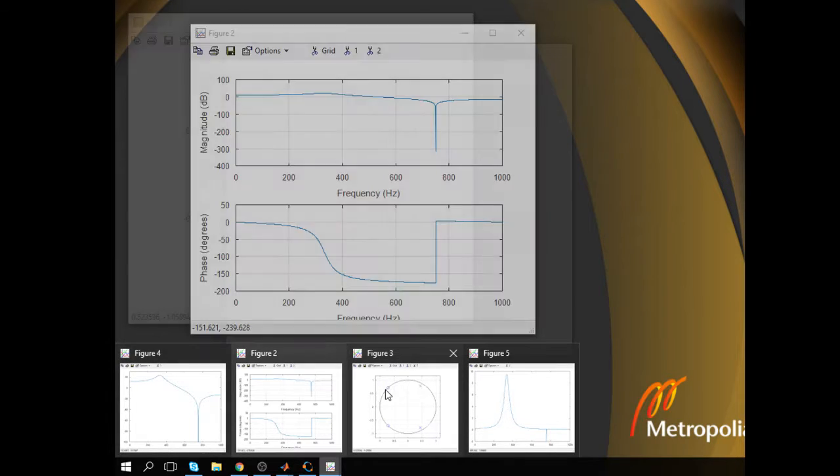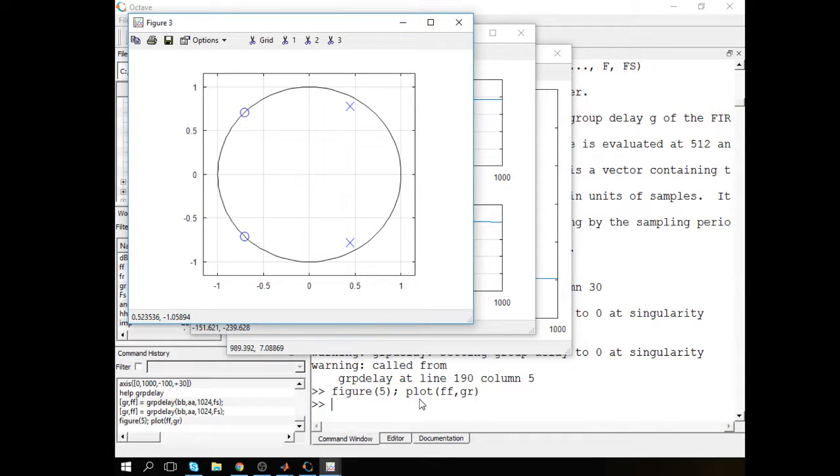One figure is missing, but anyways, this also shows that it's an infinite impulse response system. The finite impulse response systems would have these poles at the origin, or have a canceling pole, zero at the top of a pole.